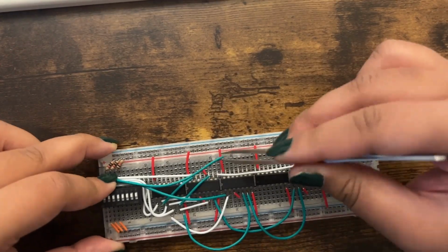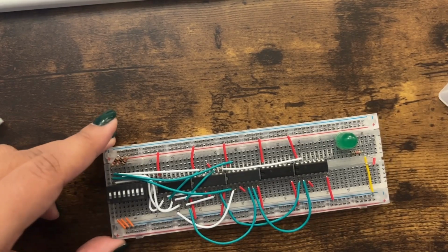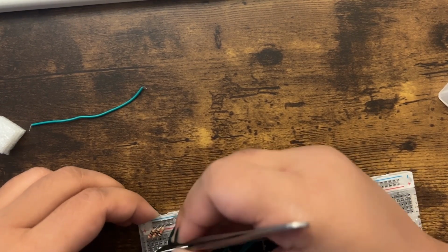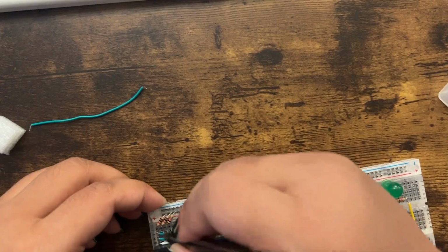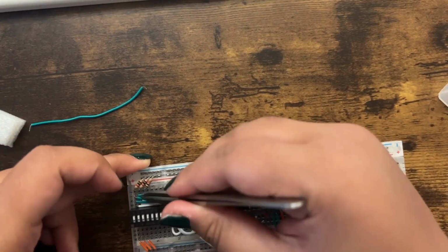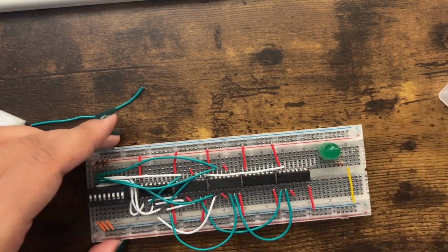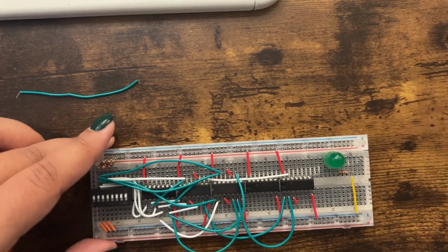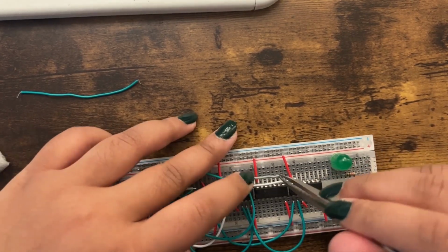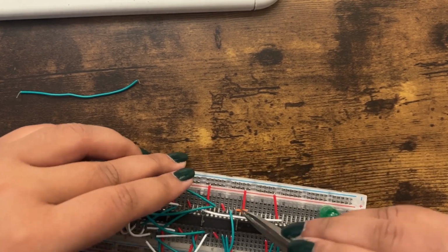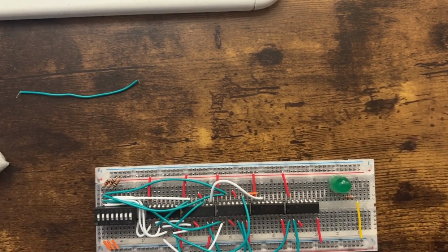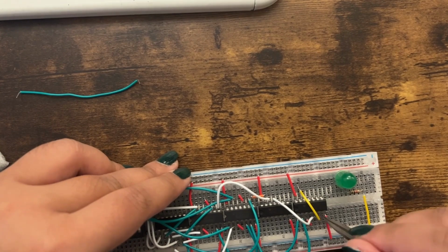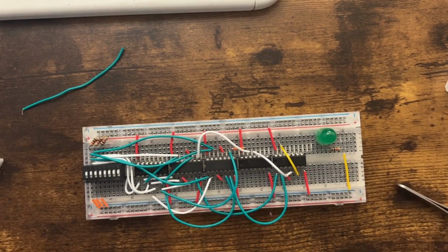And then I'm taking the output from the AND gate and putting it into the input of the next AND gate, so then I can AND the third term to it, because our AND gates only take two inputs in. So we put two inputs in, we get a term that has two of the inputs, and then we AND it with the third term to get the term that has three of the inputs. Then once we have that, we take it to the OR gate. And then we repeat this process for all of the 5 terms, and then we OR them all together. And then we connect that to the LED.